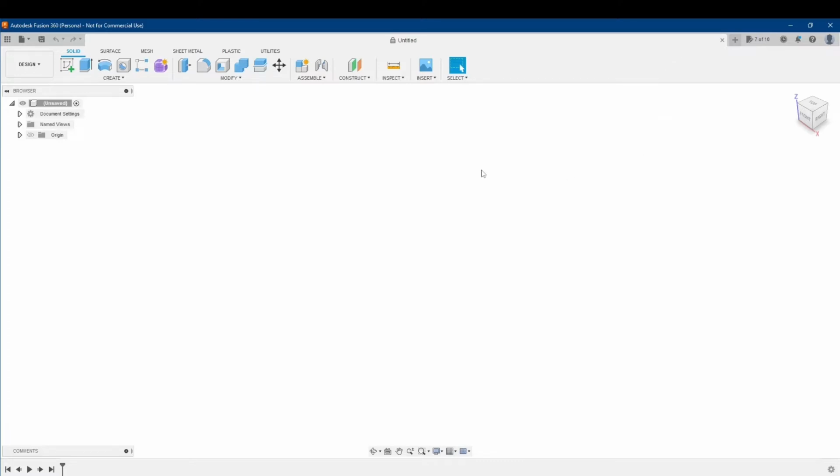Now working our way down here, this big white space here, it's your modeling space. There's nothing there now because I don't have a model or a sketch, but when there is, it'll be right here. And you can pan the view, zoom in, zoom out, orbit, and all that can be controlled with your mouse, combination of mouse, keyboard. You can all set that in your program options. And you can also control it with this view cube, which I'm not really going to mess with right now because it's kind of hard to adjust the view when you don't have anything to look at.